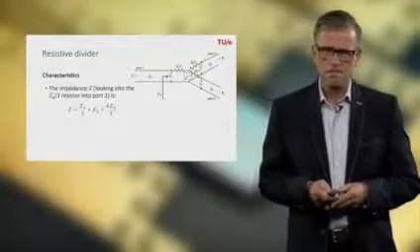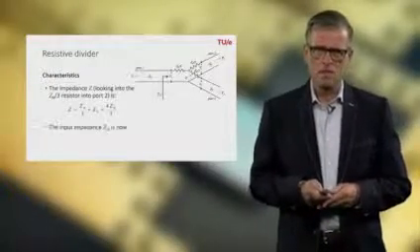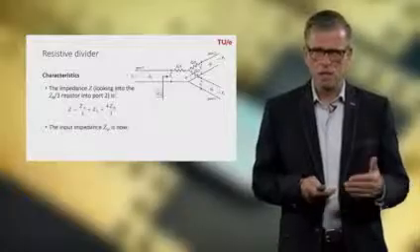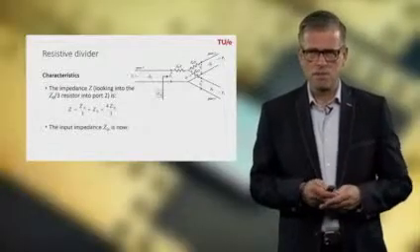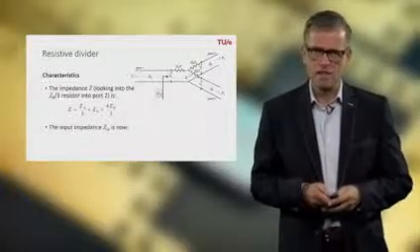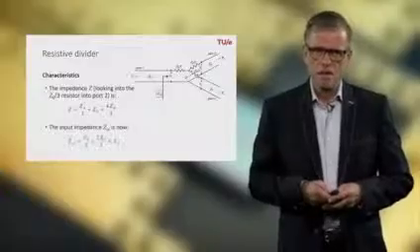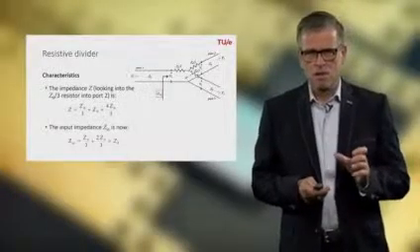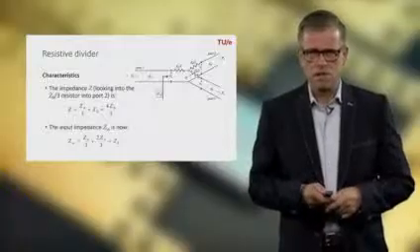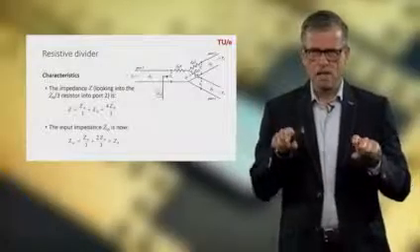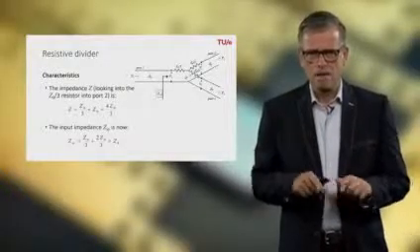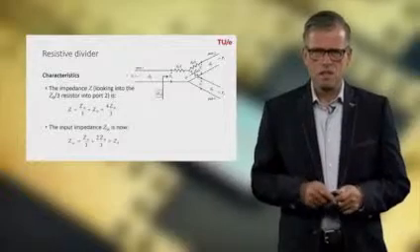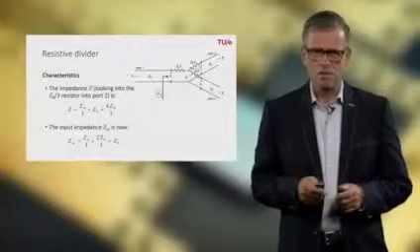Using this knowledge, we can look into the input impedance looking into the divider from port 1, as indicated in this figure. We then see a series connection of a resistor with value Z0 divided by 3, and we have two parallel circuits, each with an input impedance of 4 Z0 divided by 3.